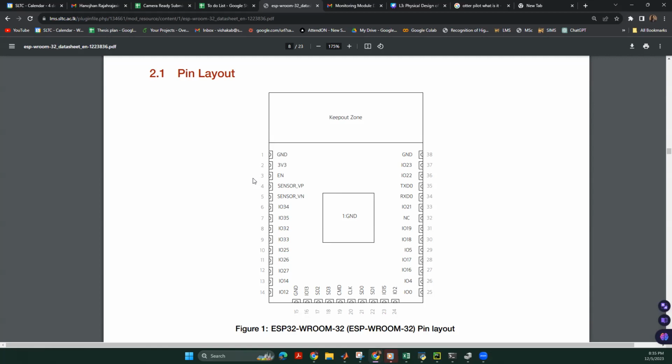touch-based interfaces. So if you want to get some kind of touch-based input to your system, which means that if you touch a certain screen, then the output voltage at this pin will be 1. By doing so, some kind of microcontroller activity can be automated. So you can run a certain algorithm once you touch the screen, right? So I hope it is clear to you that there are multiple types of pins, and including that, the touch pin is also something special in the ESP32.